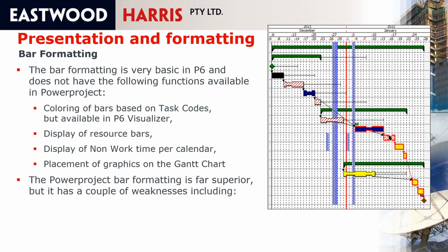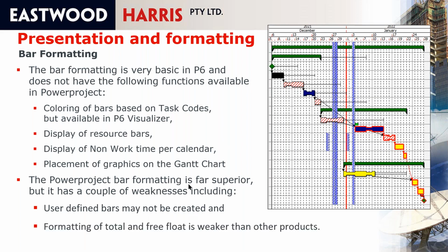So you can color the bars based on a code. You can show non-work periods, so you can see that these activities are on different calendars to these activities. It does have a couple of weaknesses. You can't create user-definable bars yet in Powerproject, and the formatting of total and free float is weaker than other products. So you can see here, these are the float bars, but these can't be user formatted. But again, it's quite clear when you've got total float, free float in Powerproject.